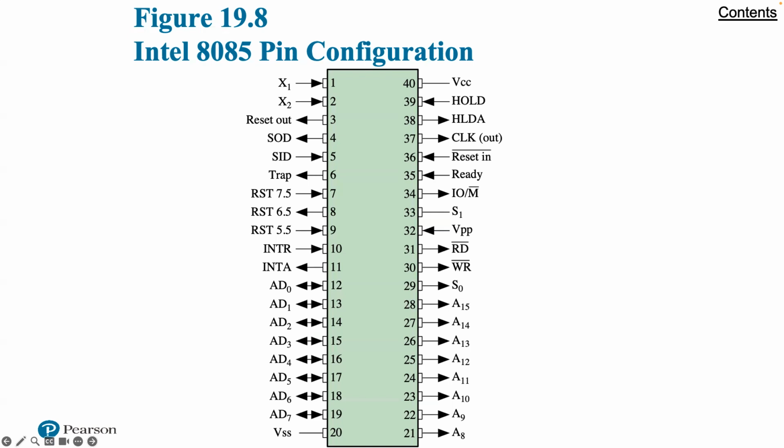Each instruction cycle is divided into from 1 to 5 machine cycles. Each machine cycle is in turn divided into from 3 to 5 states. Each state lasts 1 clock cycle. During a state, the processor performs one or a set of simultaneous micro-operations as determined by the control signals. The number of machine cycles is fixed for a given instruction, but varies from one instruction to another.